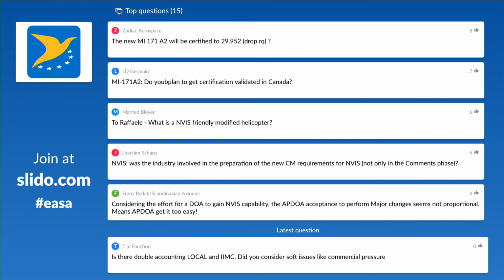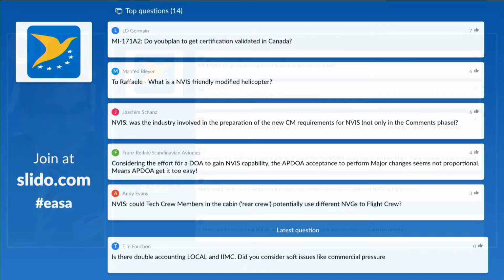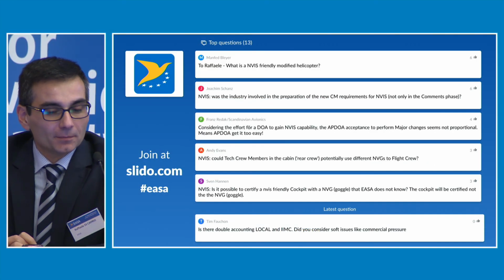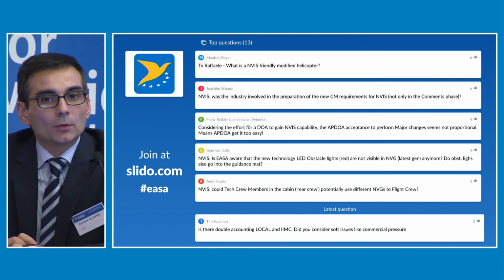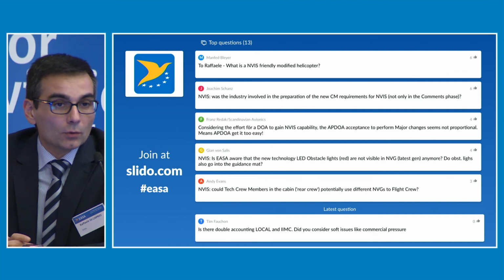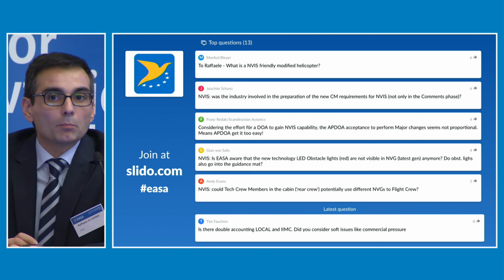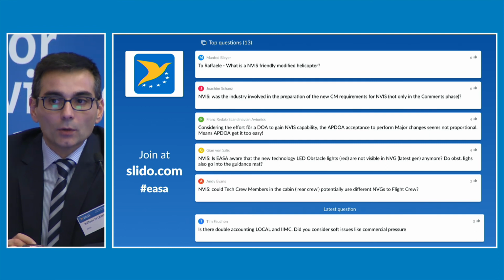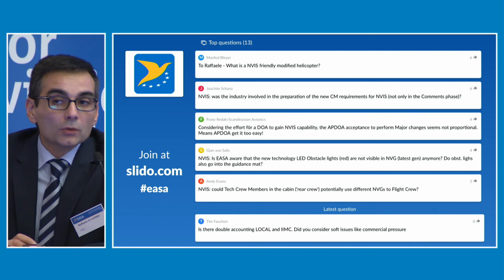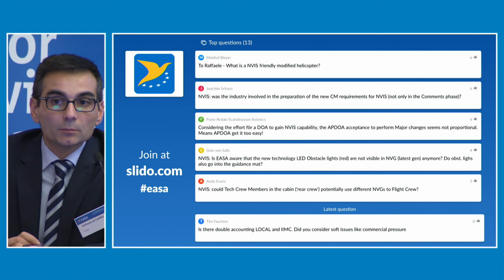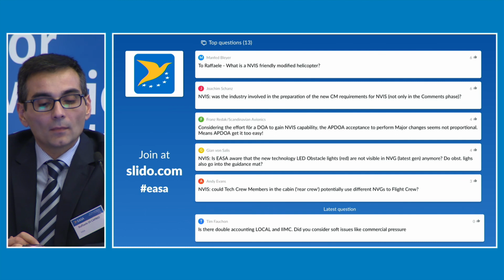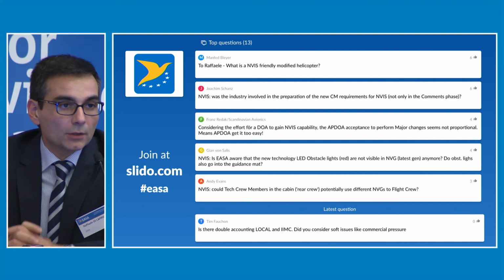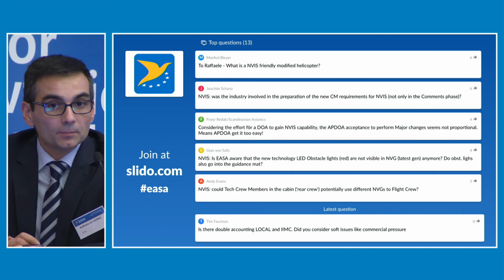Okay, next one to Raphael. What is an NVIS friendly modification? Yes, thanks, Manfred. I think you have the answer more than me. We found that some helicopters already have cockpit lighting which is NVIS friendly, so-called, meaning that all the equipment is NVIS compatible, but the helicopter has not undergone any certification on NVIS. It is most of the time sold by the manufacturer as it is, with no difference in part numbers from the other NVIS certified helicopters, other than not giving the flight manual supplement and, of course, the associated certification. So that's what we mean by NVIS friendly helicopters.